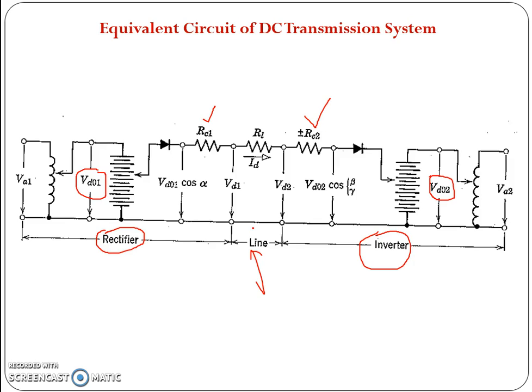There are basically 4 reasons because of which we need to keep the power factor at a high level. One is with respect to the power factor of the converter, which should be kept as high as possible. Another is to reduce the stresses on the valves and damping circuits. The third reason is to minimize the required current rating and the copper losses in the AC lines to the converter. The fourth reason is to minimize the voltage drops at the terminals of the converter as its loading increases.